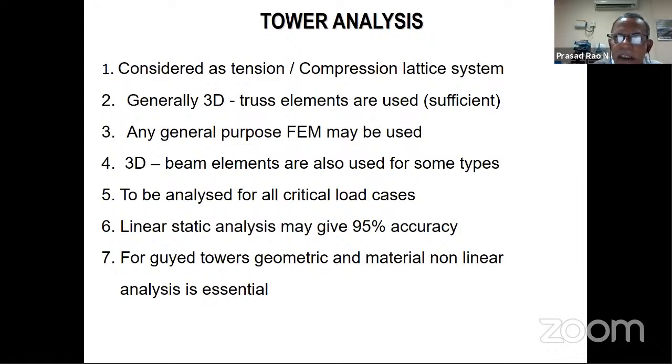your forces will increase for tall structures, where the base width is very small and the height is more, narrow base towers. There it contributes around 10%. Your forces in the members will increase by 10%, whereas linear static will show some forces. If you go for non-linear static, the member forces will be much higher than these linear static forces.